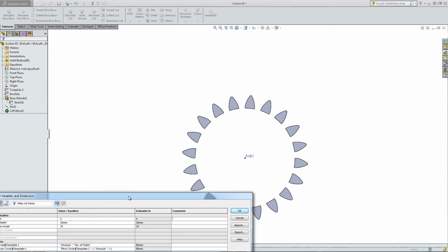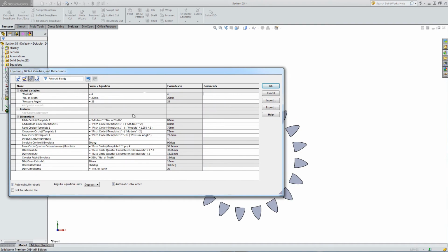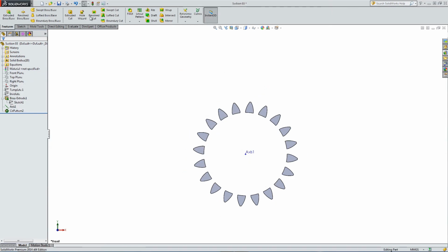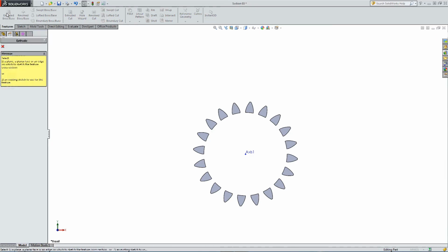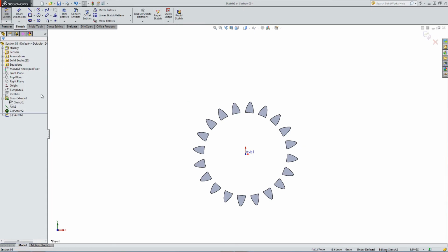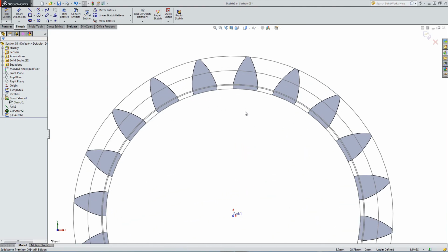Okay, so I'm just testing it out. It seems to be working quite well. Okay, right, so now we need to add the middle. So just a simple boss extrude. We're going to use the same front plane. If you want to make your gear fancy, you can. So let's just turn on one of our template sketches, and we want the innermost circle.